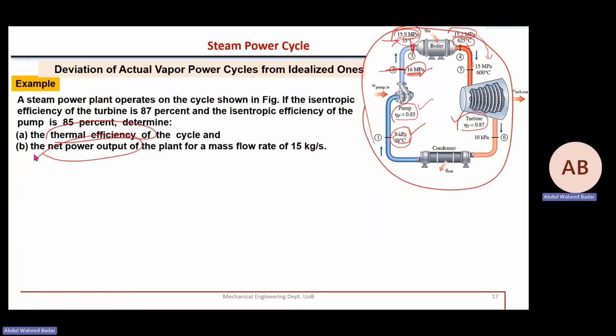And then once you make it, you check it experimentally. If there are more losses, why more? We need to find out how much. When the fluid is flowing over such a surface, can I calculate friction loss? From fluid mechanics, Darcy's equation. If this friction loss is more, do something with this surface. Maybe the surface is very rough, or maybe the fluid flow is too high. It is giving too much friction losses. Maybe reduce the flow rate.